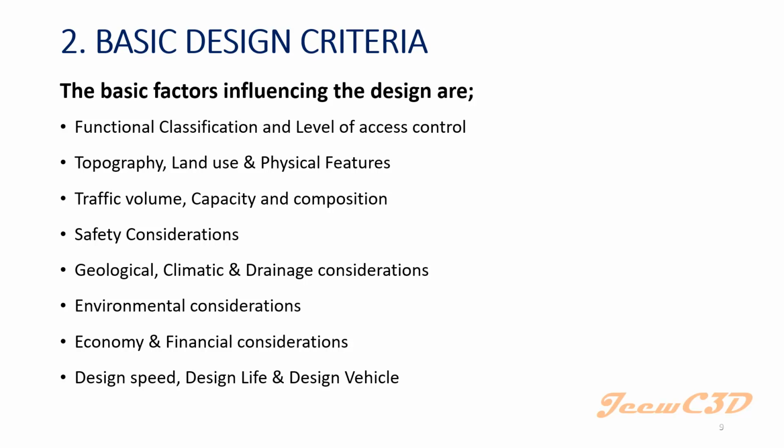But when you are doing the signboards, or by government regulations, we will tell you can't go beyond 70 kilometers per hour. That is for the safety, that we are designing the road for 80 kilometers per hour, but we are allowing only 70 kilometers per hour. The additional 10 kilometers per hour is for safety. So that is called the design speed of the road. What is the maximum speed you are designing the road?